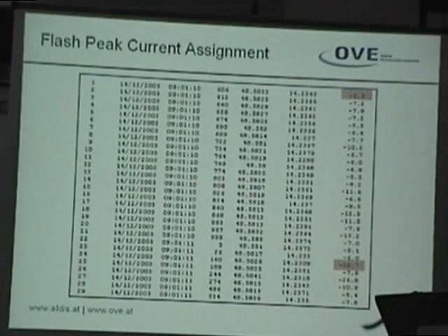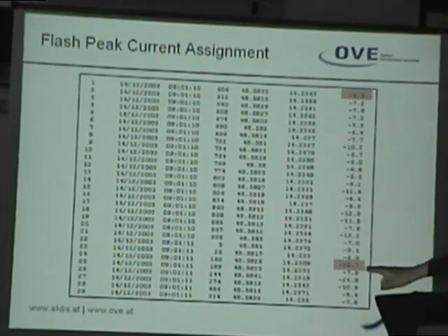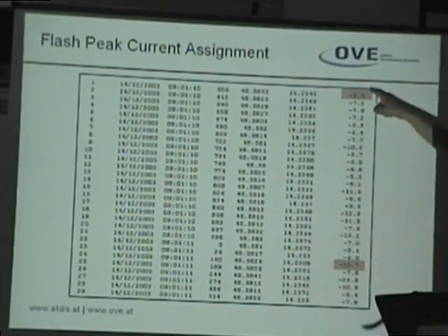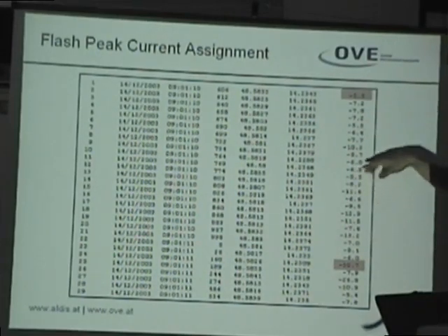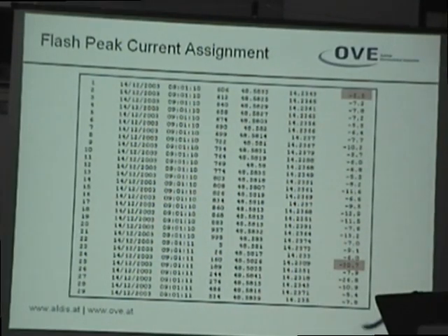This is the same flash I showed before for the windmill, and you see that the first stroke had 5.5 kiloamps, and this was the maximum stroke. So positive. In this case, probably there were some alpha components, so discharges on the initial continuing current, which is used for establishing the channel of an upward channel, and one of those is afterwards maybe a beta component.